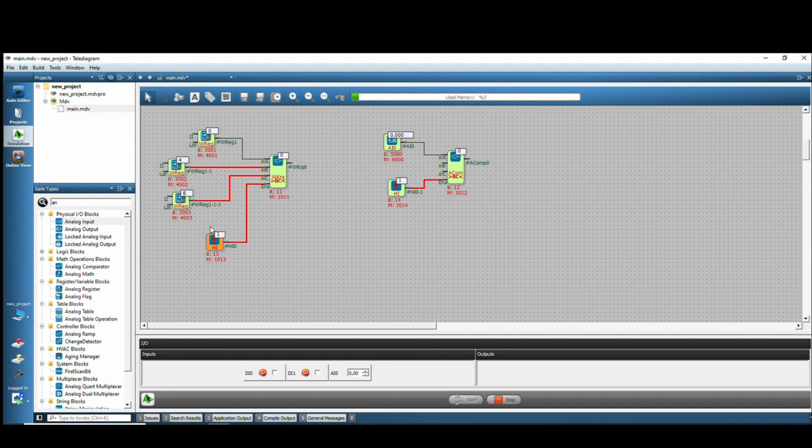You can activate it instantly with a trigger or, as I have connected a high gate for this block to work regularly, we have added a block that continuously produces 1. Let's start the test. For example, we wrote the word value 5 between 4 and 8, and the output was 1. If I change this word data to 12, it will be outside this range and will revert to position 0.